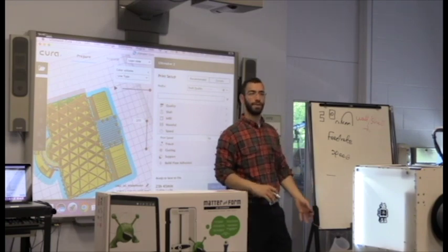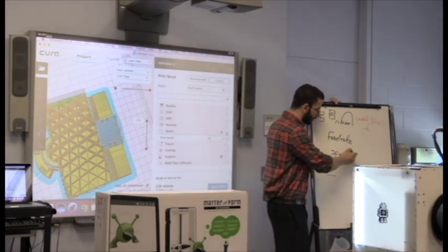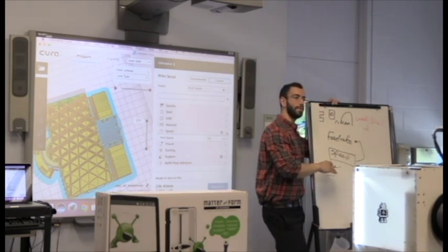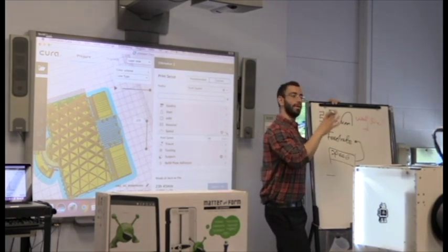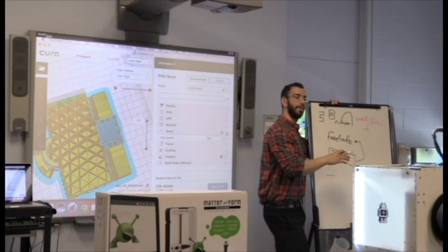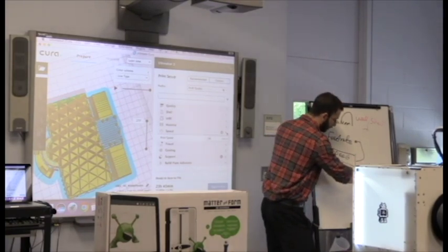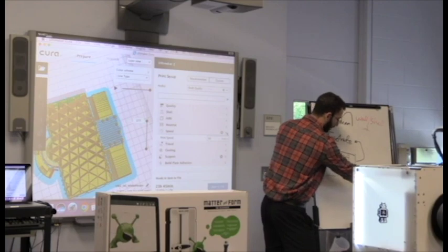You can never print too fast. However, if you print slow, usually when you adjust the speed, it adjusts the feed rate equally. It compensates for it. But remember, you can only melt so much at a time. Okay, some printers can actually print all the way to 100 millimeters per second.